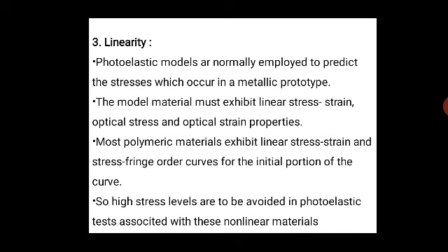The third property is linearity, which depends upon the loading applications and the linearity of the behavior of the member. Photoelasticity models are normally employed to predict the stresses which occur in a metallic prototype.